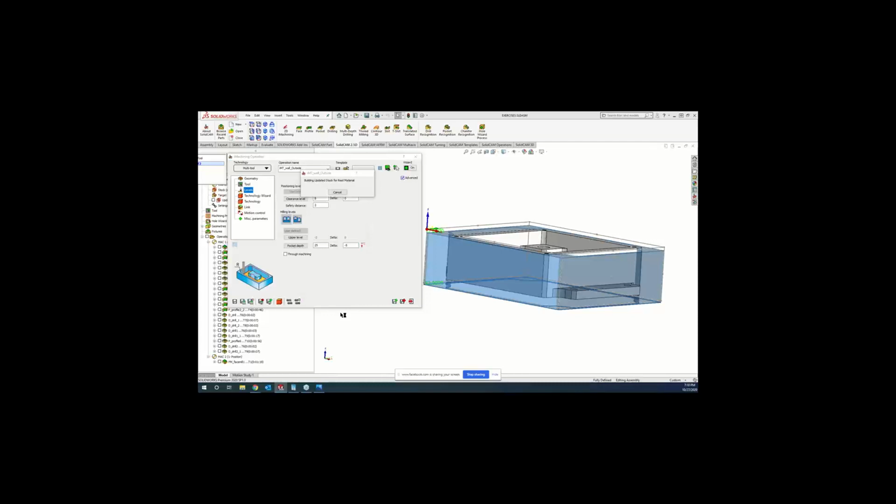Now, hopefully when we get Kevin back, we could get him to show maybe some of the multi-tool functionality, because as we can see in the blue highlighted areas there, the radiuses didn't exactly match up. So we're using a larger tool for roughing, but what we can do is actually bring in the same operation, a tool that's closer in diameter or smaller in diameter than the radius is on the part itself. So hopefully he gets back here shortly and he can show that off. And we'll ask him to do that.